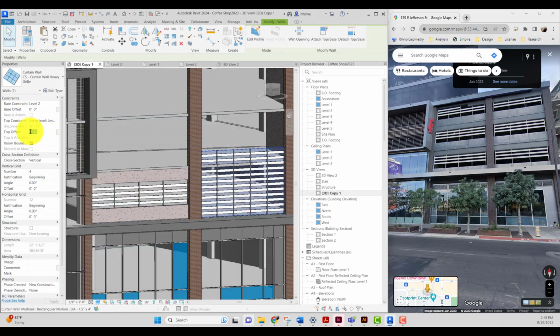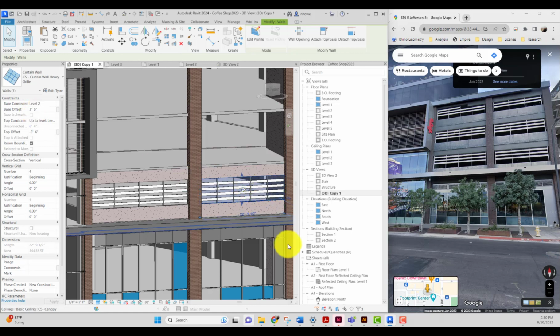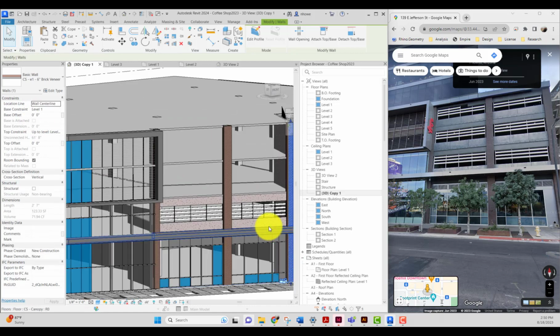Shows up. We'll go ahead and tweak these. -3.6, 3'6". What I'm doing to get the 3'6" is I'm going 3 spacebar 6. That space will mean it's shifting from feet to inches as far as Revit's concerned. Okay, now this is cool.